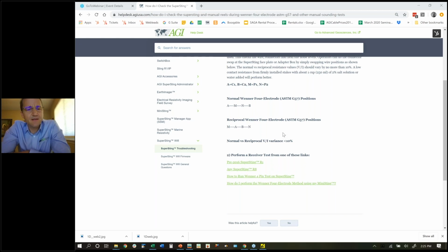Preferred method is again the generator with the AGI generator power supplies, simply because it's lighter versus the deep cycle marine battery. The default is to use the deep cycle marine battery. That's out of the box. There's an additional accessory if you want to run the generator. You do not want to take the 12 volt off of something else, such as the 12 volt directly out of the generator. That would cause a problem.